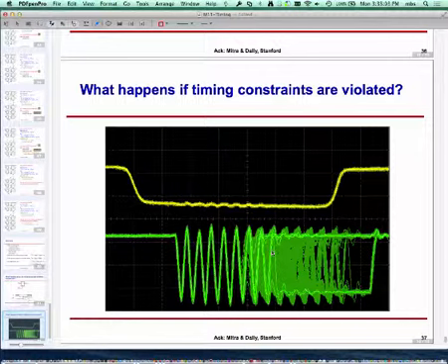It's basically that you were expecting the waveform to be high, and then it goes into this oscillation. This should never happen in a digital system. Digital system voltages correspond to either logic 0 or logic 1. What you're seeing here is some jumbled voltage, which is neither 0 nor 1. It's supposed to be a straight line, or a clean transition from 1 to 0, right? So it's spending a lot of time in this middle zone, just oscillating away. It's not a digital system during that time. It's neither 0 nor 1.